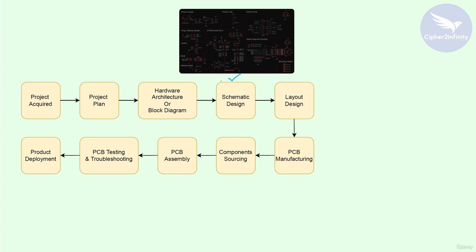Here he does the detailing of each and every block, like the power supply block, and if there is a controller, he creates the circuitry of that controller. He selects the ICs, and the different components connected around that circuitry. All those things related to circuit designing are done in this phase, which is the schematic design phase.